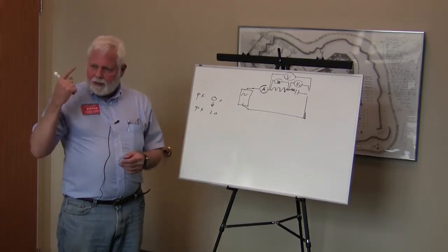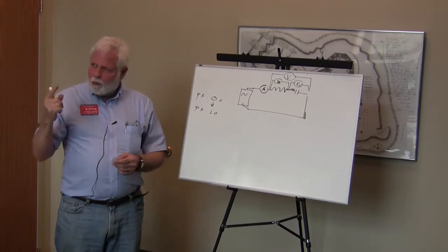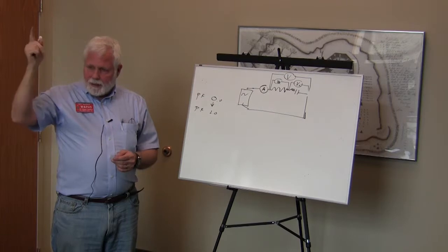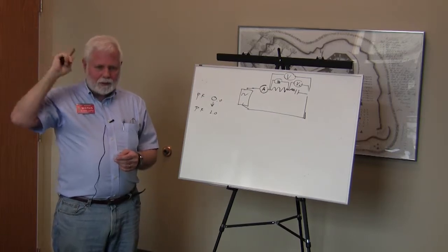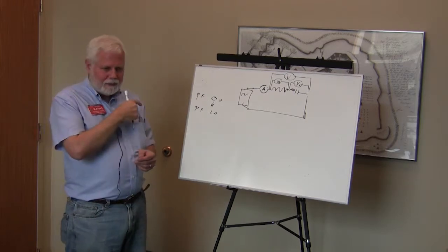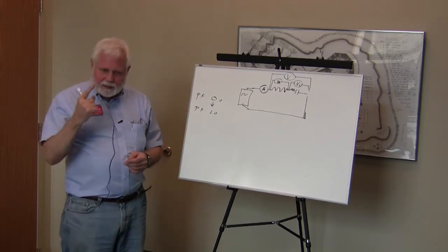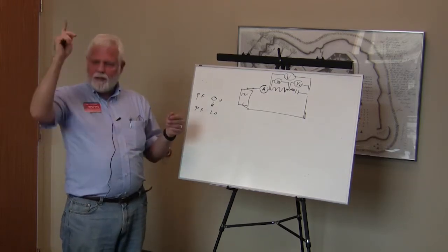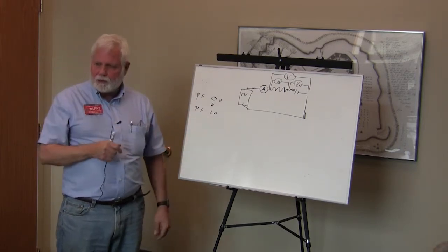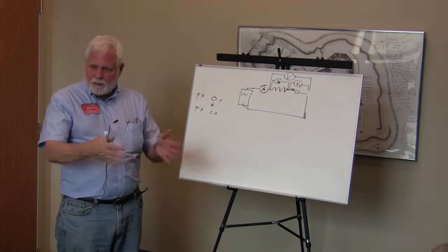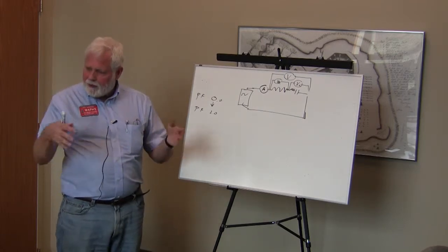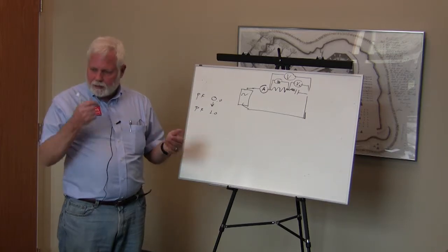The only things in your house that have a power factor of 1 are incandescent light bulbs, or like the heating element in your stove or your clothes dryer. A pure resistance incandescent bulb or a heating element would have a power factor of 1. Compact fluorescent light bulbs and everything else have a power factor somewhat less than 1.